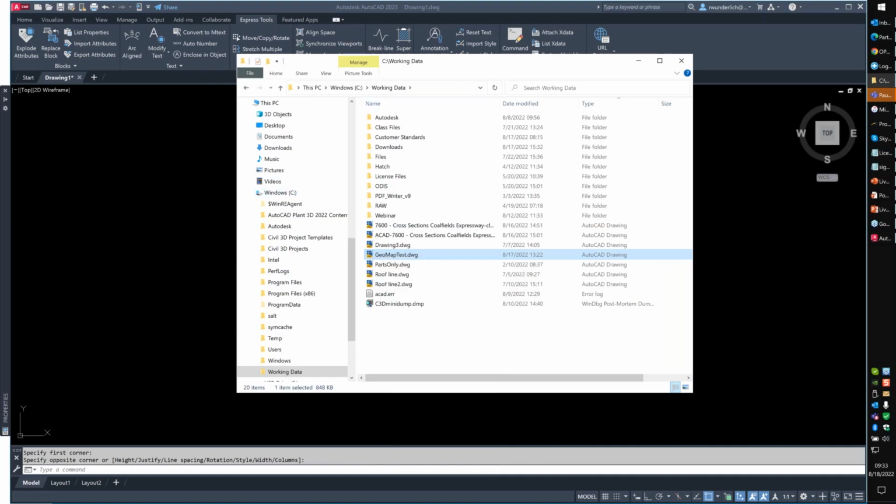Let's go back up in here. Can you demonstrate using parametrics in a block to change the length of an MLine or a PLine? Laura, that's dynamic block information. We could probably do a webinar on dynamic blocks, because that's going to be more than a two or three minute conversation. Basically, you have a couple of parameters you need to set when setting up a dynamic block using parametrics. You have to have a base point. You have to have a stretch or lengthen associated to those objects, and there's a couple of bits and pieces that all go to make that work correctly.